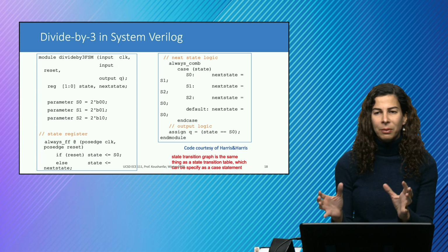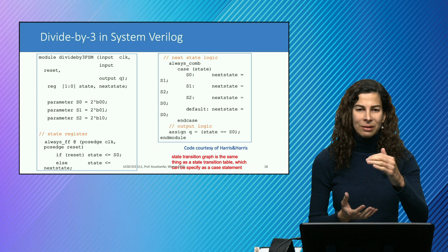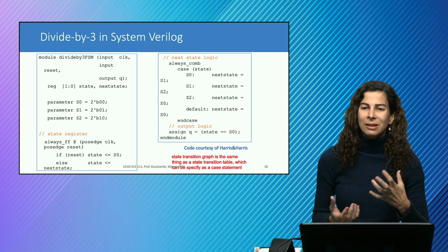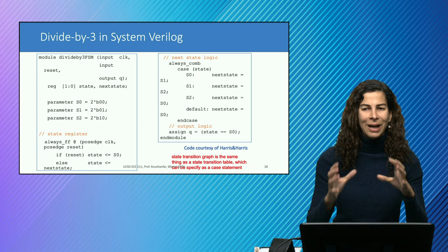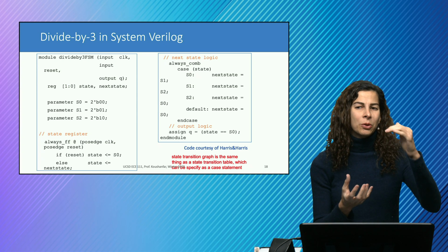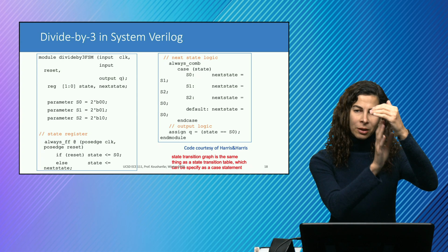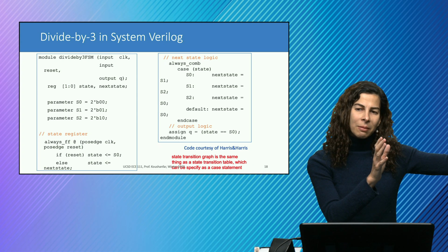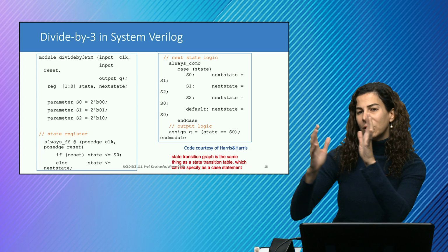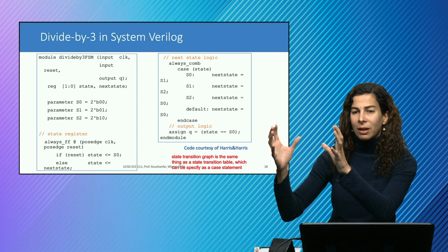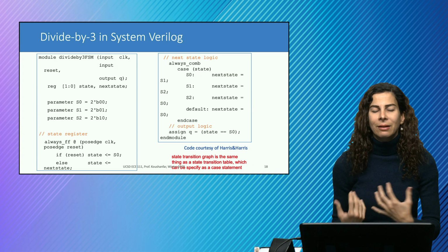there is a template, and I like that because it keeps things clear for me. The template follows what we had for a Moore state machine. Remember, we had that block diagram which said your next state logic comes from the current state in the registers and the inputs applied, and then the state goes through a combinational function to generate the output for us. So let's divide it like we said.